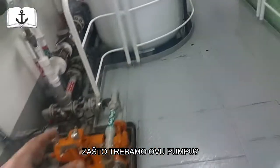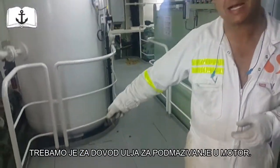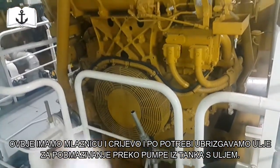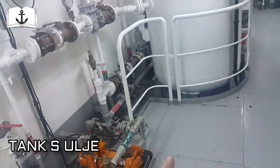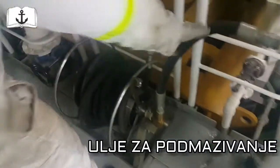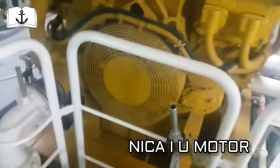Start from the beginning. This lube oil pump, why do you need it? You take the lube oil from the storage tank to the engine, to lubricate the engine. Yes. And you have here the hose, and you're just putting the hose to the sump of the engine and the top of the element. Exactly the same as you're doing with the car. From the lube oil tank, it's going through these lube oil pumps, through the lube oil lines here, through this hose. Then you connect it to the engine, and you top up the level in the sump. Exactly. Okay, good.